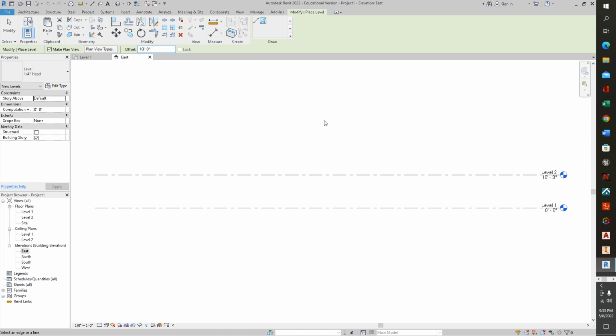And the way that we add in levels at this point is, once we've selected our offset, just below the ribbon, there's this bit called offset, on the left, just left of the center. We can take our mouse and gently, we don't have to push the button yet, hold it over just to show that there is a phantom line that shows up above the level 2. We don't want to go crazy clicking things, because that will just add levels.